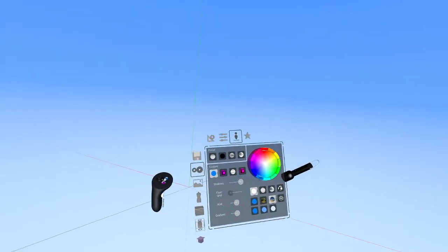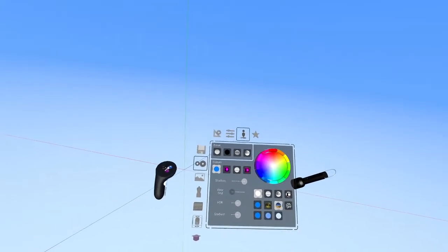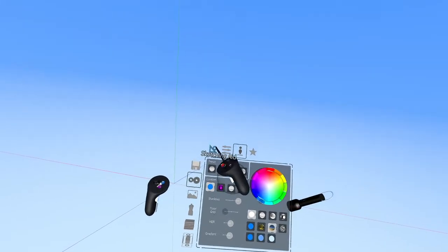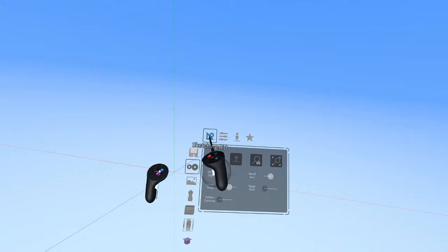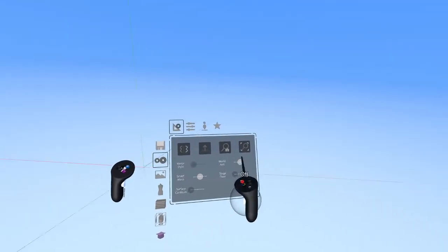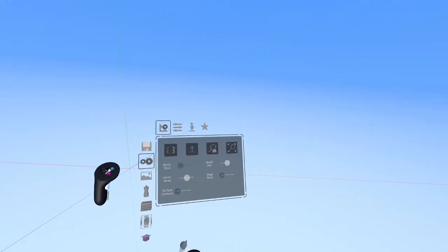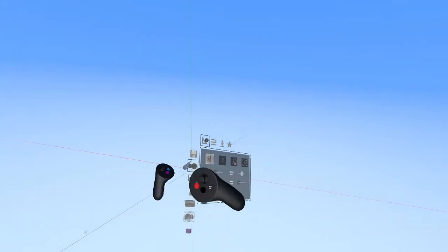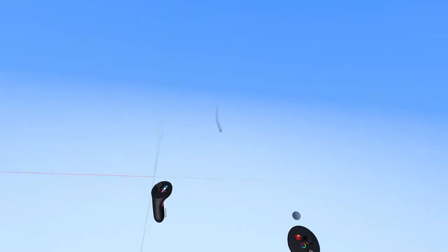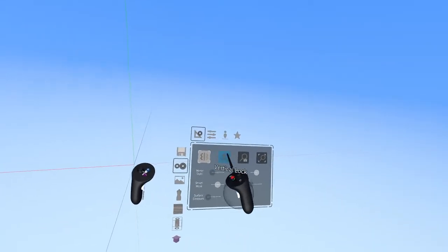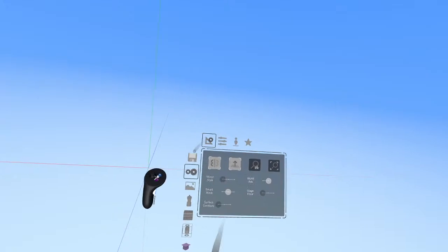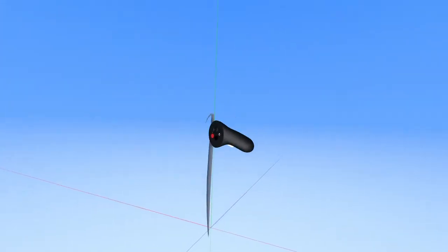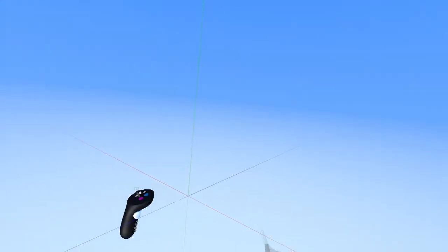Okay, awesome. Next thing I'm going to do is actually set up a few things that I like to use before designing something or starting a project. So for that, same section, Settings, but I'm going to go into this subfolder up here called Sketching Aid. And we already have World Axes on. That's great. We're going to leave that on. And I'm going to turn on the mirror option right here, which now we can start sketching symmetrically. And then this is an option that I turn on and off throughout sketching or designing something, which is vertical lock. And that's just going to make it so that the y-axis is always facing up, and yeah, it just adds a little more control to your space.